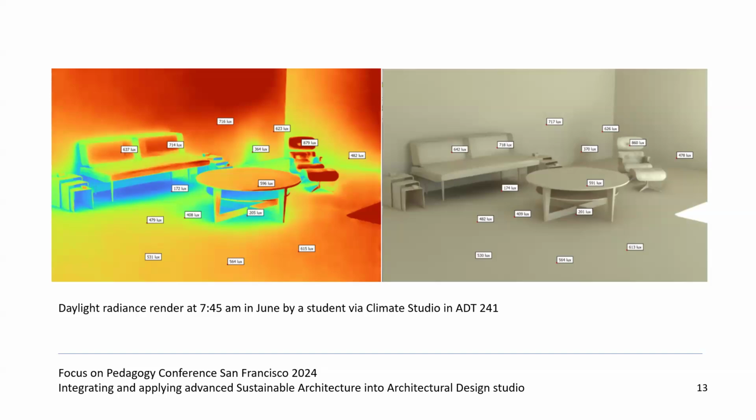Now, as you can see, the highest lux in this picture is on the chair, I believe, which is 879. And if you ask why we have it on the chair, it's because the light comes from one of those walls, and we have direct sunlight. But since the elevation angle of that direct sunlight is very low, it's only 879 lux.